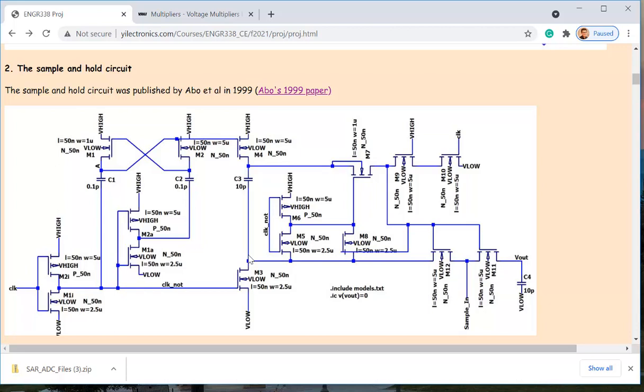So I have a cap, right? It's going to dump charges to it, a lot of charge, and then disconnect the two terminals. What's going to happen to the two plates? It's like a floating VDD over there, so the charges have no place to go. So the two plates are like a battery with the charges stored from the previous cycle, and then it's ready to be supplied to the next stage over here. Okay.